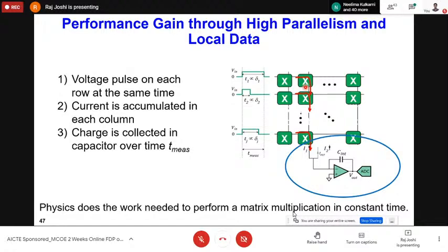And these are arrays which are shown here. If you can do that on every single array simultaneously, that is called parallelism. And you can accumulate those currents inside the memory, if you assume that an array means memory. It could be volatile or non-volatile memory, but we are striving towards non-volatile for the advantages of analog calculations.